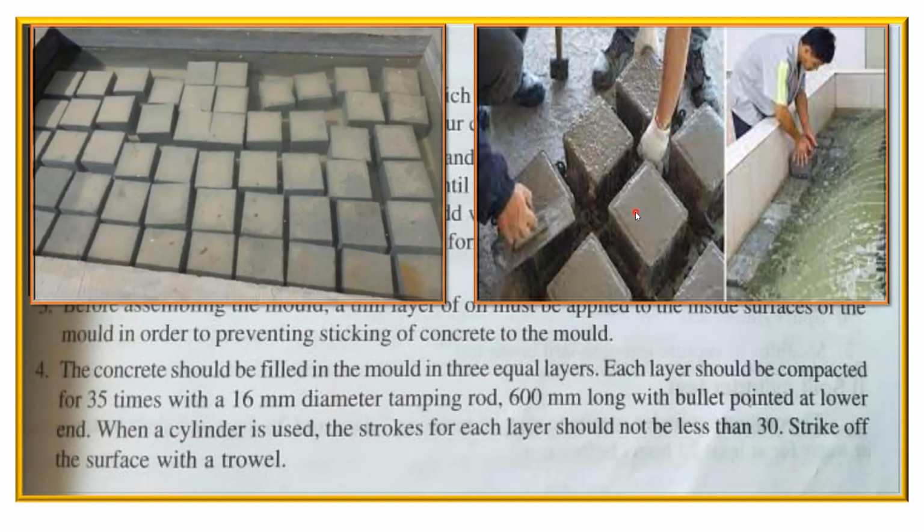So once this is done, the next day you have to come. Let us say you are doing the concreting of this. Next day you are going to come, take it out, and do the demolding. Immediately keep it in the curing tank for curing purposes. This is how you keep them in a curing tank, right? You have to cure it for 28 days.